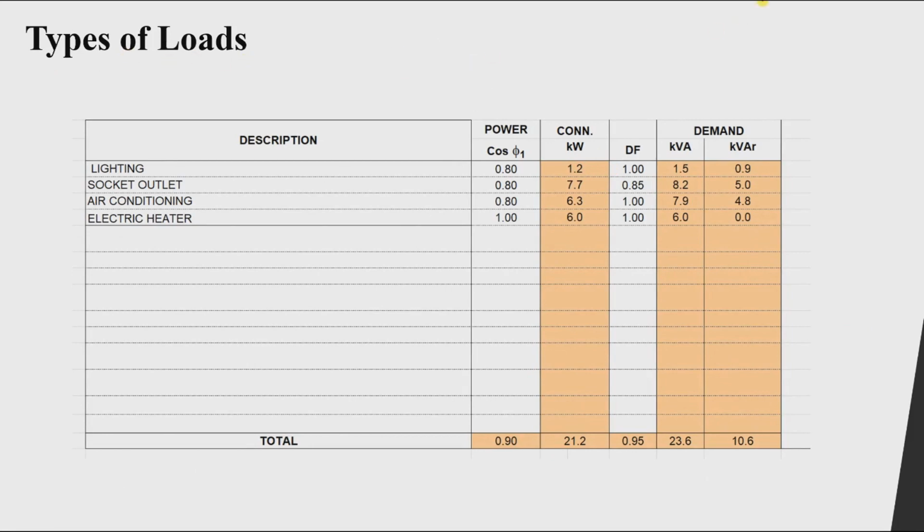If we look at this panel schedule that we will learn inside the course, after designing our circuits for lighting, for power, etc., you will find we have these loads and their equivalent connected load in kilowatt. Here we have them in kilowatt, and we will divide each by the power factor to convert them.